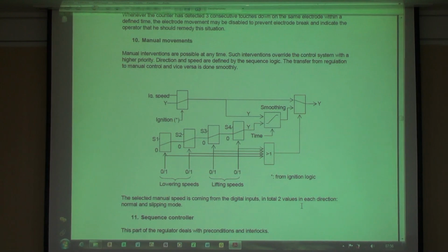Why I ask the question: in emergency case we use the accumulator. It's no problem because of the accumulator pressure and flow rate. Sometimes we use some diesel pump, and at that time I want to know what speed is normal or proper.